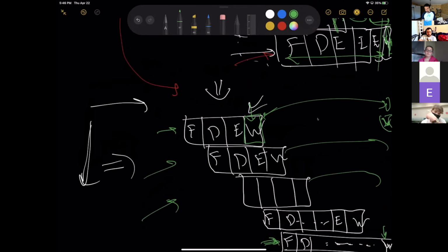But this reordering, without taking care of when you are writing to or changing the architectural state, obviously violates the von Neumann model. So one important thing I wanted you to understand is when things go wrong when you violate this property: when exactly you change the architectural state. And the architectural state of the program will change in the write back.